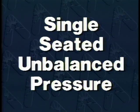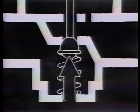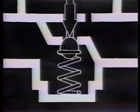Now let's look at the valve plug and seat. These components not only affect the regulation curve, but must be selected for the type of fluid to be controlled and the desired tightness of the seal at shutoff. A single-seated, unbalanced pressure valve is the simplest and least expensive design. The term unbalanced pressure indicates that when the valve is closed, upstream pressure to the PRV is entirely brought to bear on one side of the valve. On the other side is the force of the set point apparatus and any back pressure in the system. In other words, the pressure across the valve plug is unbalanced.